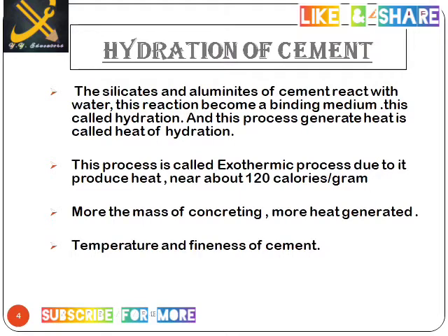The greater the mass of concreting, the more heat is generated. The temperature and the fineness of cement mainly affect the heat of hydration. So, hydration of cement is basically the reaction between the silicates and aluminate materials and the water.